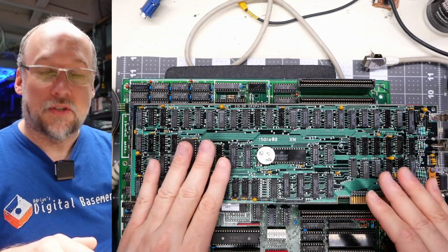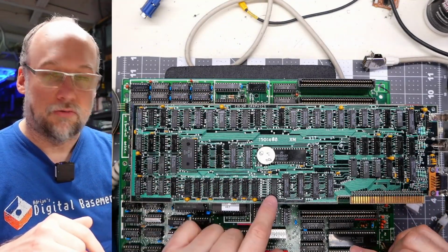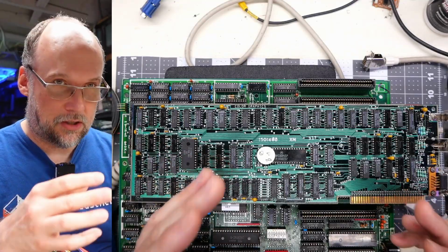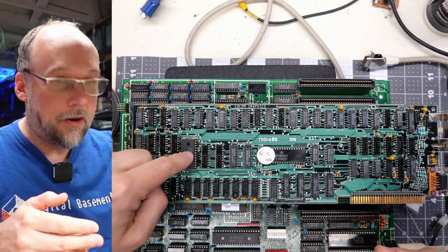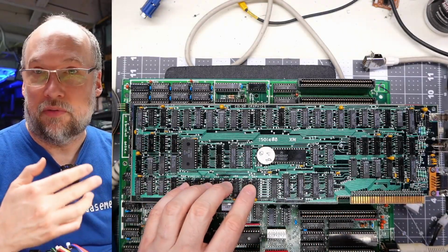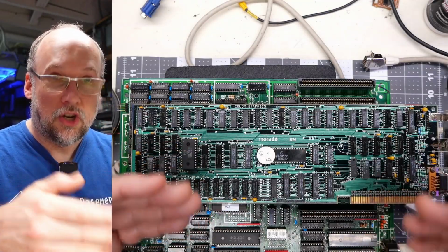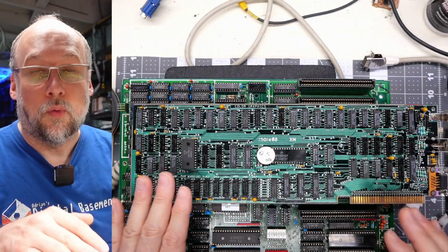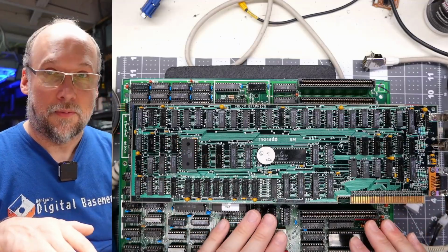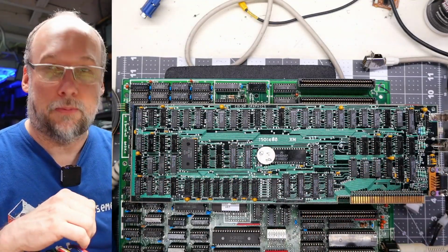The 6845, which is this IC right here, is what's responsible for essentially displaying the contents of RAM to the video output. And this card is running at a 60 Hertz refresh rate, so 60 times a second, it's actually reading through the entire RAM, well, the part of the RAM that's displayed on screen, and then using the character ROM right here is converting that to letters on your screen, and there's part of the RAM that's used for the attributes, for that color or blinking, things like that. And that all happens constantly, 60 times a second, no matter what you're doing on the computer. There's no interaction from the CPU when it comes to displaying the video buffer on the RGB output.